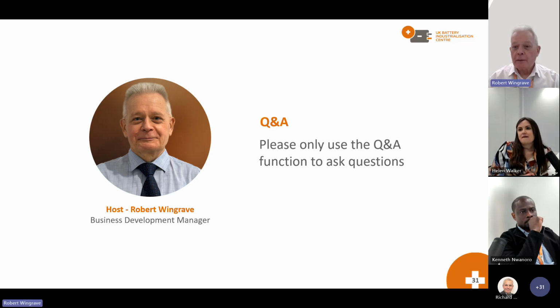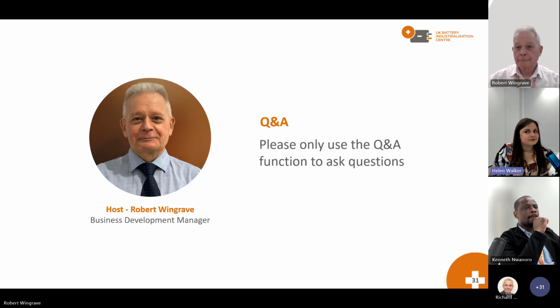Thank you, Brindley. We have a question from Sanglam. Is the surface tension assumed to be a constant value for coating simulation? Yes, it is. And sometimes people follow that question with, is your contact angle a dynamic contact angle or not? And we just use a single value for our contact angle.